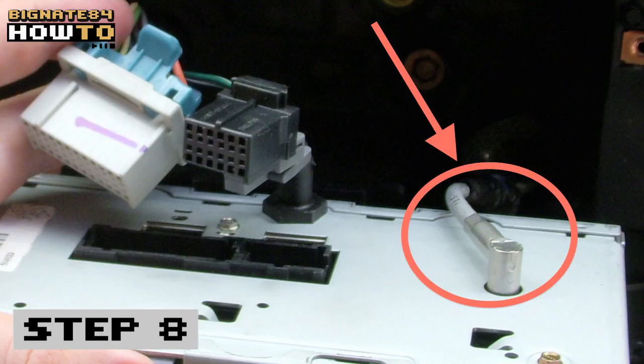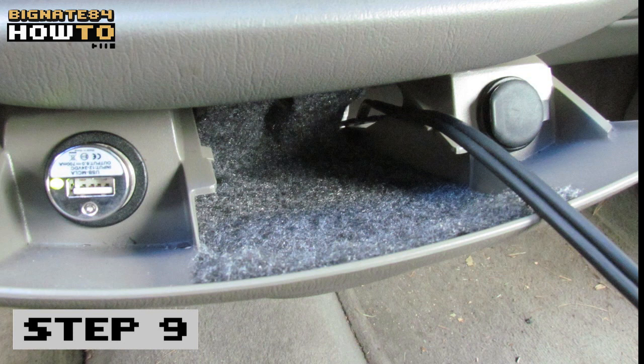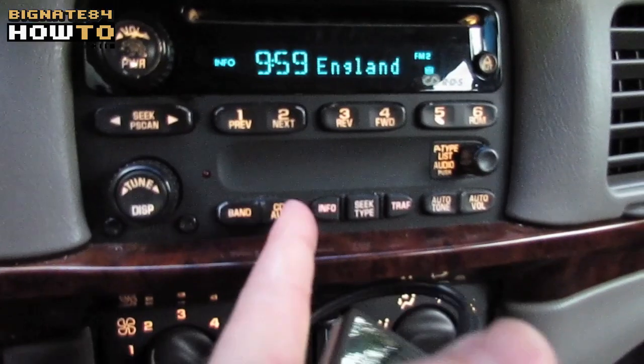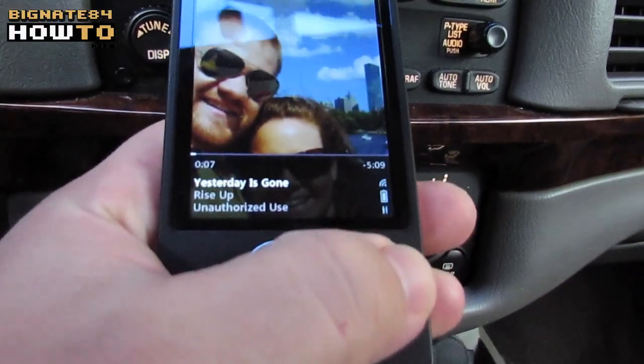Step 8. Don't forget to plug the antenna in. It can be a huge waste of time and source of frustration if you forget this step. I know from experience. Step 9. Put the radio and the dashboard back in place. Secure some fabric with glue or Velcro to the inside of the compartment. This will add a more finished look and keep the MP3 player in place. Now when you press the CD aux button on your factory radio, you can listen to your aux input source.